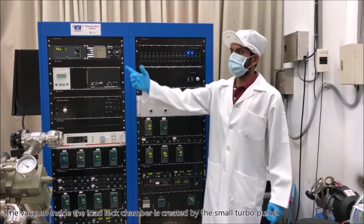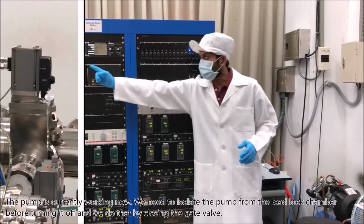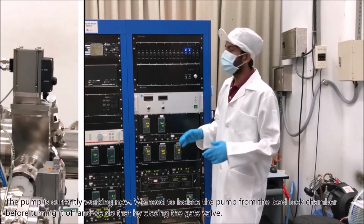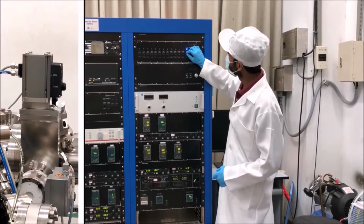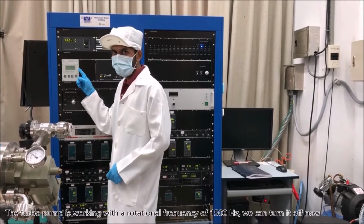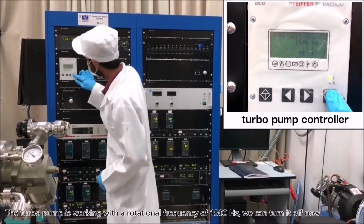The vacuum inside the load lock chamber is created by the small turbo pump. The pump is currently working now. We need to isolate the pump from the load lock chamber before turning it off, and we do that by closing the gate valve. The turbo pump is working with a rotational frequency of 1500 Hz. We can turn it off now.